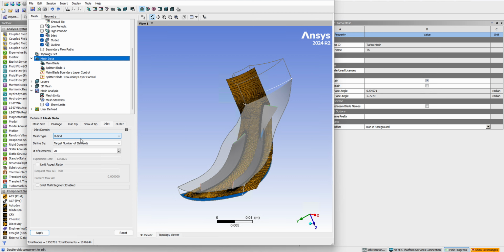Another thing you can do is explicitly control how fine the mesh is in different regions. For example, in the inlet region the flow is slow and there is no wall, so you can use a coarser mesh so that more mesh can be distributed down there. I picked the value 20. I think it probably can be a little bit coarser.